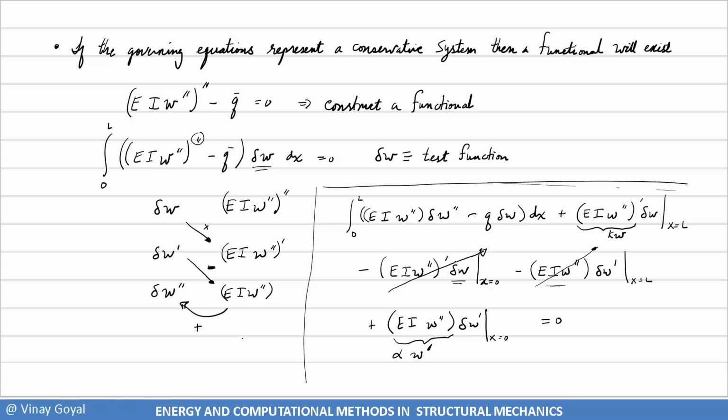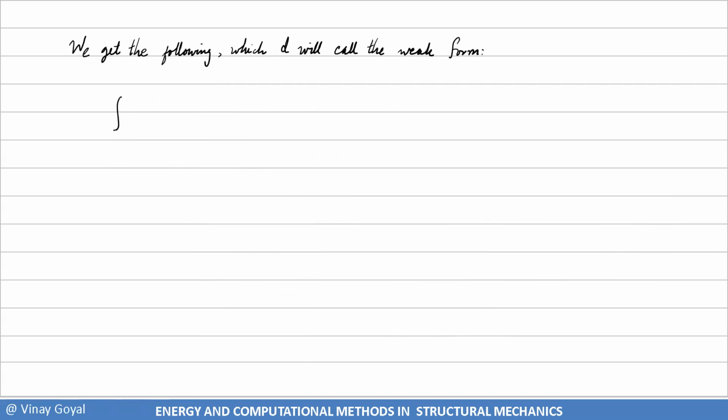And so if I do that, I get the integral from 0 to L of EI W prime del W prime minus Q del W dx.